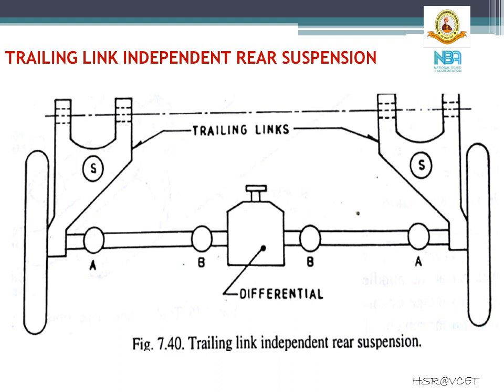The springs, which are represented on the figure, are the coil springs with shock absorbers mounted concentrically within them. The trailing links hold the wheels firmly and also sustain accelerating and braking forces. It is claimed that the combined metal rubber mounting responds softly on straight roads and increases ride comfort. When cornering, they resist lateral force with a reliable stabilizing effect, even when the car is fully loaded.